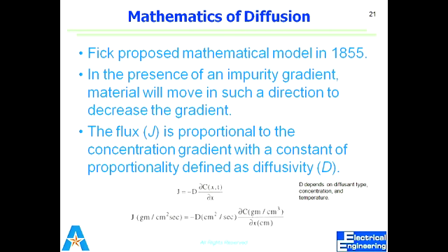You can do it in any way. You can put it in a gaseous environment that contains that particular dopant, or you can spin on dopant on the surface. That is solid, and you can spin on dopant. This is what we'll be doing. We'll be spinning on phosphorus dopant on the surface, and this is pre-deposition.